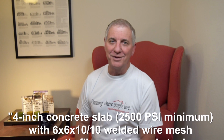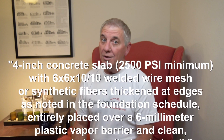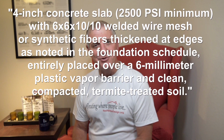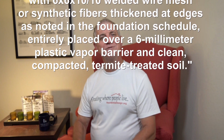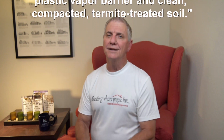For example, most of what I design sits on a slab on grade. And one note that gets placed slap dab in the middle of all those slab plans is this: 4-inch concrete slab, 2500 psi minimum with 6x6 by 10/10 welded wire mesh or synthetic fibers, thickened at edges as noted in the foundation schedule, entirely placed over a 6 millimeter plastic vapor barrier and clean compacted termite treated soil.